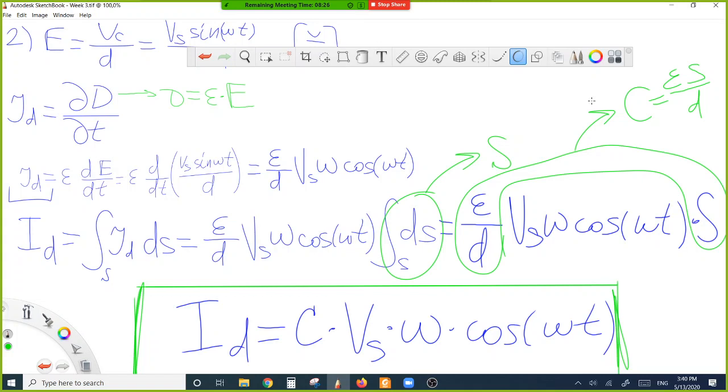Here we have an example in which the displacement current is actually necessary to account for the behavior of the circuit. In the absence of displacement current, we must assume that current cannot flow through the capacitor. In circuit theory, displacement currents are not normally used or assumed. You assume that current doesn't flow through the capacitor.